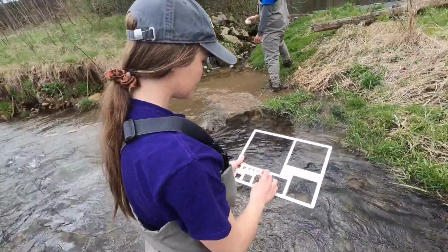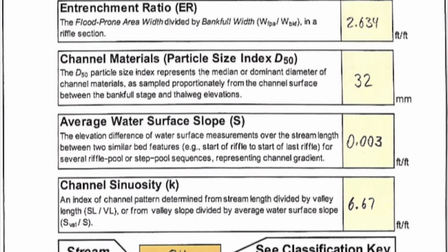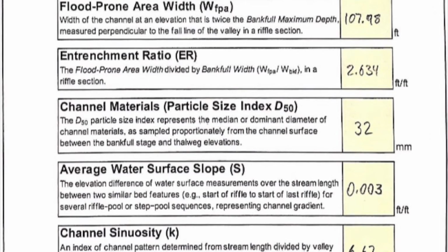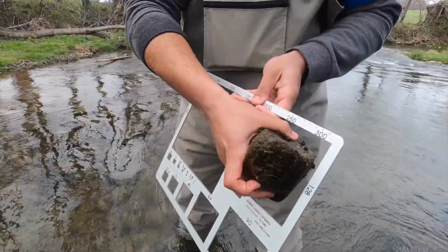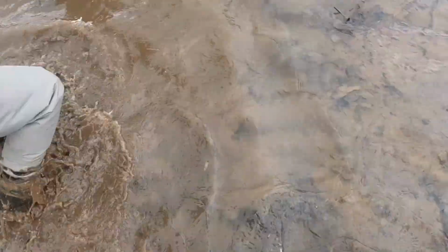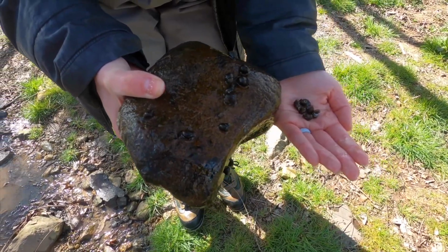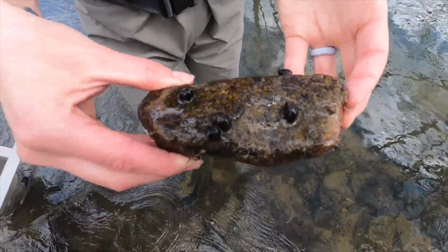The pebble count assessment is used to assess the stream bed material. This assessment plays a major role in classifying our stream. We are physically taking 100 samples from the bottom of the stream and measuring them on a gravelometer. We don't want to see any sort of fine silt because that's starting to show characteristics of an unhealthy stream. Normal sized aggregate that's very clean is ideal for the stream and shows that it's operating healthy.